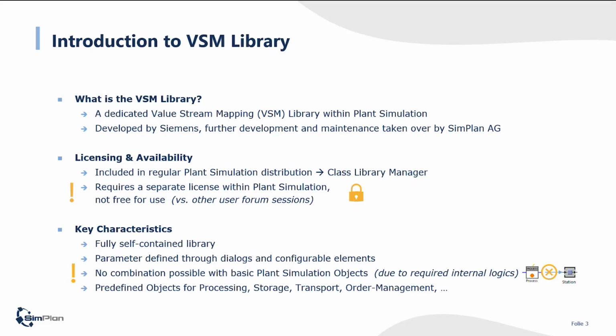And then basically we have predefined objects. We will see them in the toolbox for processing, storage, transport, and also, importantly, the order management. So how are orders flowing through the system? Maybe one short note afterwards: there is heavy internal usage of SQLite and memory databases. So if you save run models, maybe after 5 days, and you reopen it, you would need to restart your simulation because a memory database is not persistent on a model.